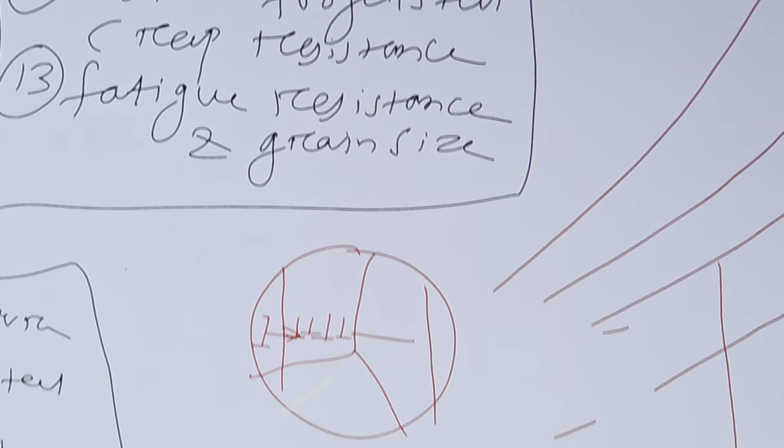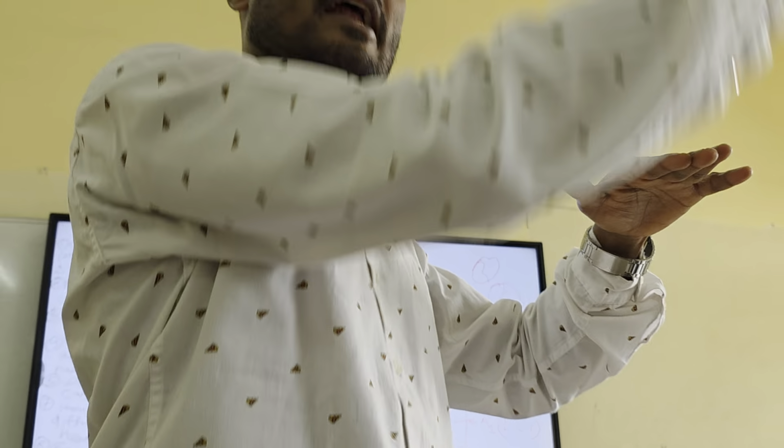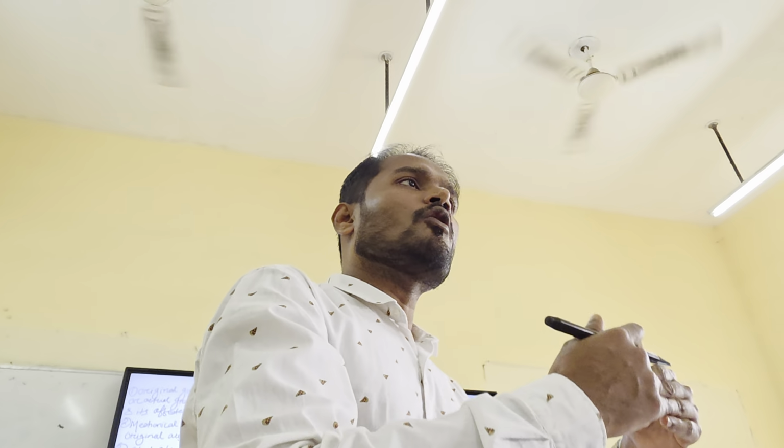Dislocations want to glide, but they will interact with a grain boundary. The moment they interact with a grain boundary, they cannot go to another grain. They will stop there. So that is called piling up of the dislocations. So due to dislocation pile-up, what will happen? Dislocation interaction will also happen, right? There will be a back stress. One dislocation will apply stress on the next dislocation, like this. That means this dislocation will apply stress on this one, so they cannot move further.